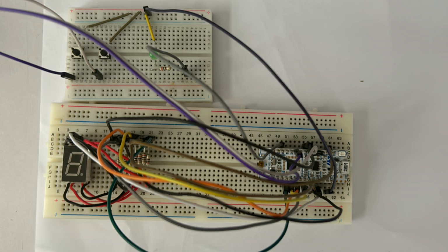I'm Syed Muhammad Harisha, and I will be presenting the hardware verification. For this project, we have two inputs, which are a push button for entering and another push button for exiting the car park. For the output, we also have two types: a green LED as the indicator for parking availability and a common anode 7-segment that will display parking usage. When the parking is full, the LED will be turned off and the 7-segment will display FULL.